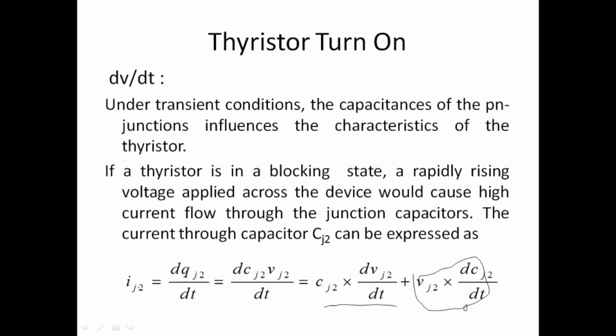If it continues and alpha 1 and alpha 2 reach a high value, high anode current will pass, so it may turn on the SCR. That is unintentional, correct? We are not expecting such turn-ons, and it may damage your SCR also. So we should control this phenomenon.